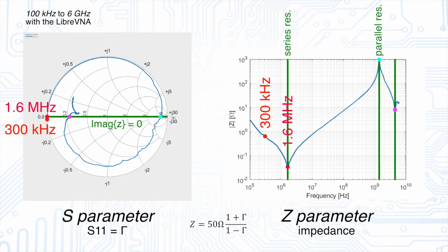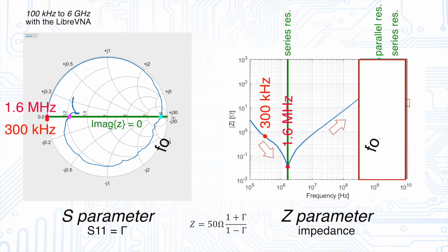Each series resonance is followed by a parallel resonance, and vice versa. In the impedance curve, this means a steady up and down. But believe me, measuring anything above the first resonance requires a really high level of measurement skill.